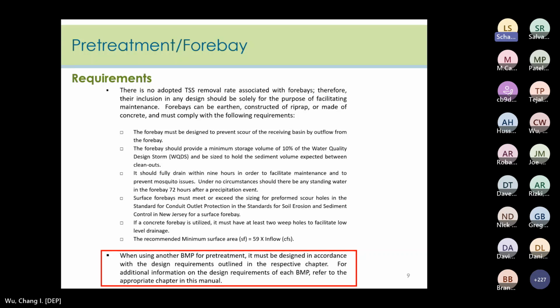So even if there was a compliant waiver or variance, the sand filter with underdrain still does not merit the 80% TSS removal rate, and the design itself does not meet the water quality standard. So had this project been approved after the delayed operative date of the rules, the project would still not be compliant, and the municipality would have been out of compliance with the MS4 permit requirements.